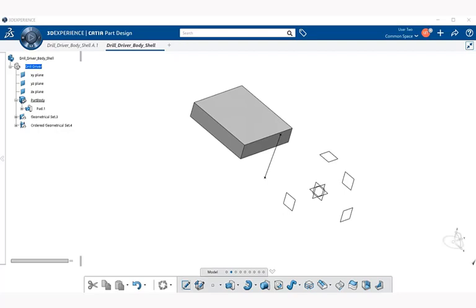One of the most important things to remember when working with standard geometrical sets is that the feature order, or timestamp, is not taken into account. Unlike modeling in a part body or an ordered geometrical set, where each feature that is created subsequently becomes the in-work object. So let's look at some examples of the differences between the part body, having a geometrical set, and an ordered geometrical set.